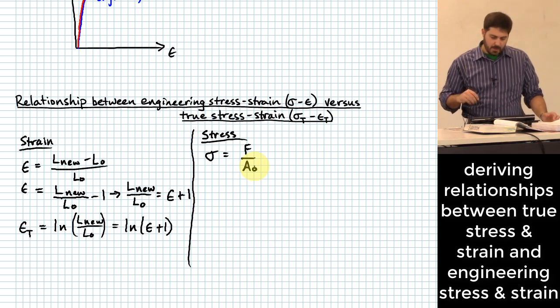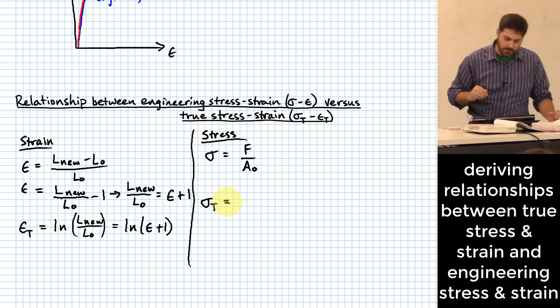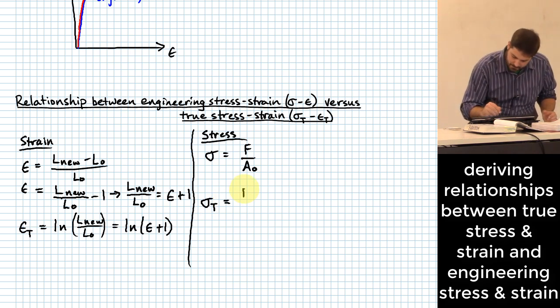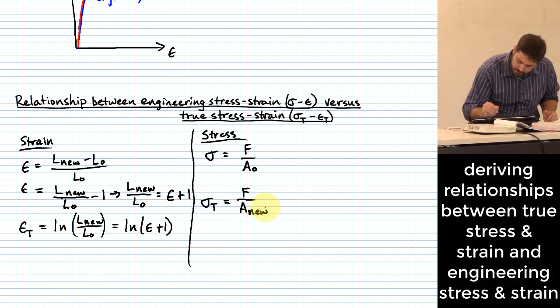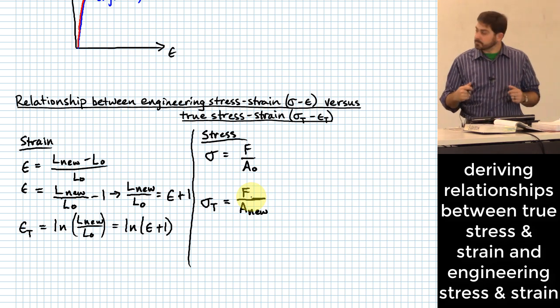Well, what if I change this up and I want my true stress? How do I get my true stress? Force over actual area, which let me call A new, because that's where it got to with this test that I just showed you.